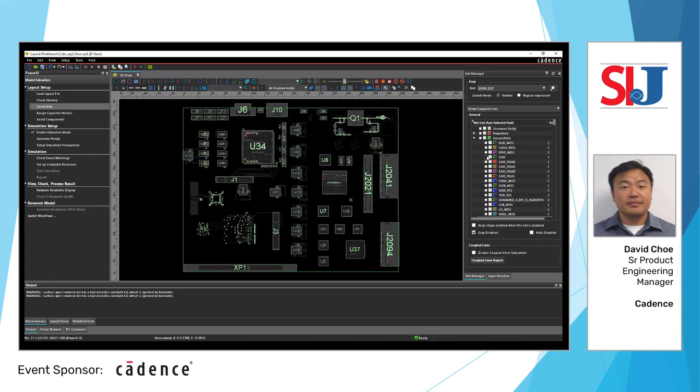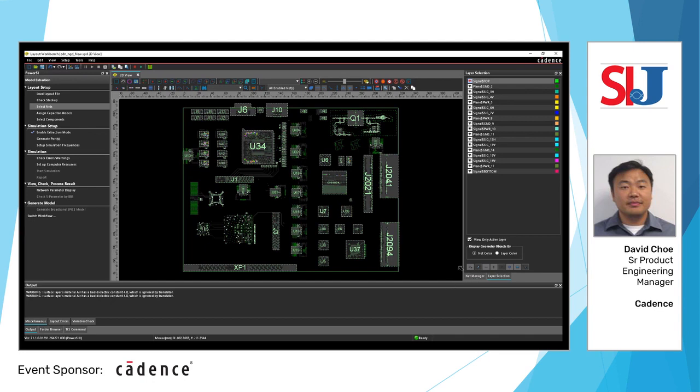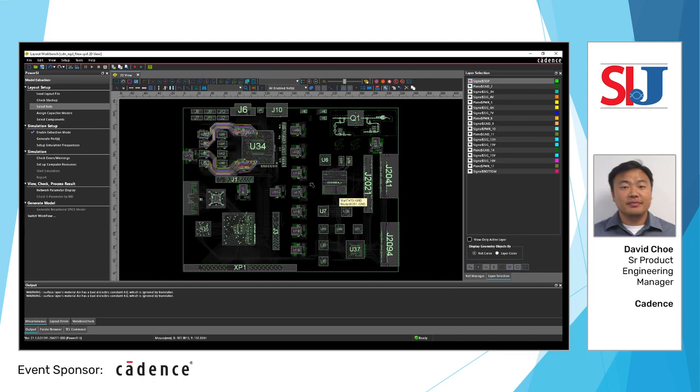The next thing you need to do is to turn on a reference net, which is ground, and let's take a quick look at all of the geometry, minus the shapes. So what we see here is the DDR interface is fully selected, and even some of this section over here, which is just part of the same name. The ports that we're interested in are over here.